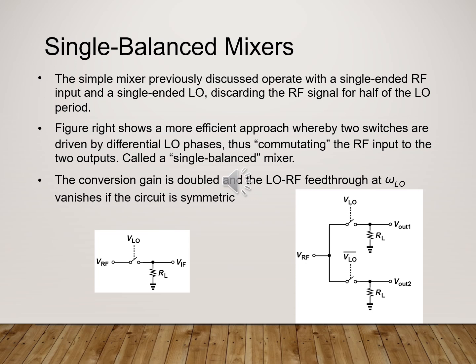Single balanced mixers. Now, we have active or passive mixer implementations. One can be passive, with gain less than 1, or active, with gain more than 1. Each has its advantages and disadvantages. The passive implementation using diodes as nonlinear elements or switches, or MOSFETs as passive switches, always accepts conversion loss rather than gain.